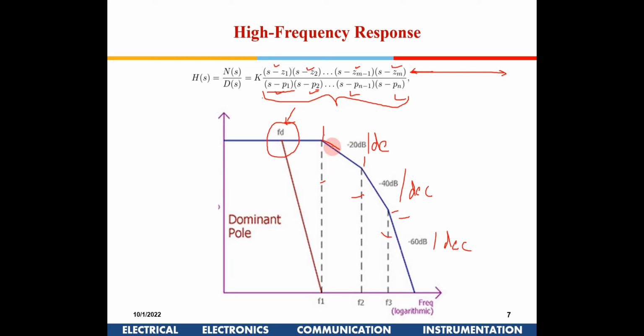Okay. So see, every pole is a place at which the frequency starts falling at 20 dB per decade. So you add one more pole. This pole corresponds to the RC value which you get out here. Okay, this S is equal to P1. So this pole will be decided by the RC value. There will be several capacitors and resistances in a circuit. Each of those capacitors will contribute towards one pole out here.